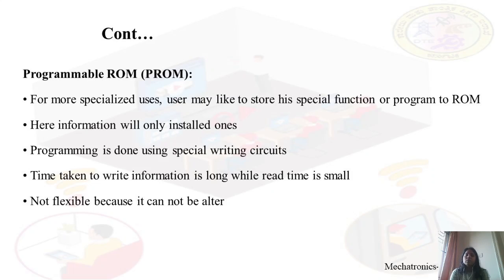So more specialized users may like to store their special function or program in ROM. Here, information will be installed only once. That means we cannot reprogram this again. Programming is done using special writing circuits. The time taken to write information is long, while read time is small. It is not flexible, because we cannot reprogram it. Understood the PROM? That is, PROM is the programmable read-only memory.